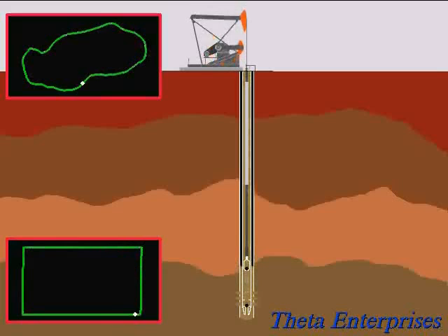The reason why these animations are so accurate is because we actually use the wave equation to develop the data that went into the animations. The pumping unit kinematic calculations that we have in our software, which are an exact way of modeling the pumping unit, were used to create each frame of these animations. We use the actual dimensions of the pumping unit to build the exact frame, so everything is exactly to scale.